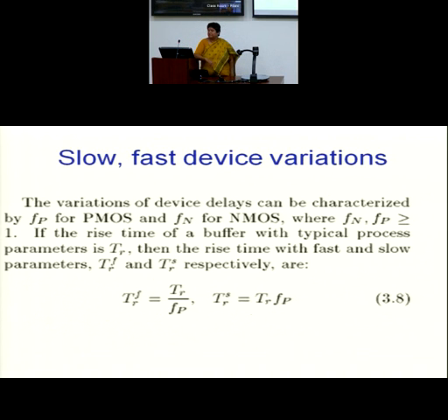Now what can happen in a device? Why device mismatch? What happens when device mismatch happens? Device becomes either slow or fast. Because of that, with different inverters, some NMOSes can become slow, another NMOS can become fast. So even if I am designing them equally, I may get a pull down delay mismatch, I may get a pull up delay mismatch. So let me characterize the nominal rise time and fall time, nominal high to low delay and low to high delay.